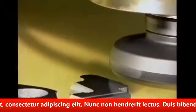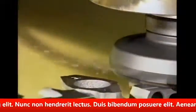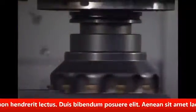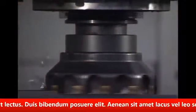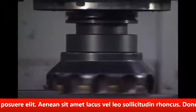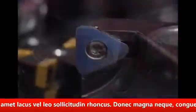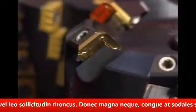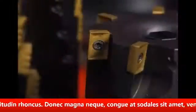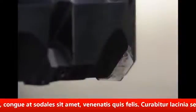Fine pitch cutters are used primarily for milling cast iron or for finishing work. Coarse pitch cutters provide a large gullet space necessary for milling ductile materials or in wide cuts. They are chosen for everyday work. Milling inserts are available with various grades and shapes. In addition, milling inserts have their own corner geometries, including the radius and the wiper flat.